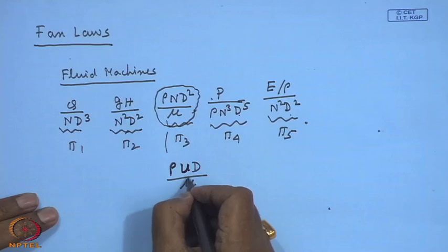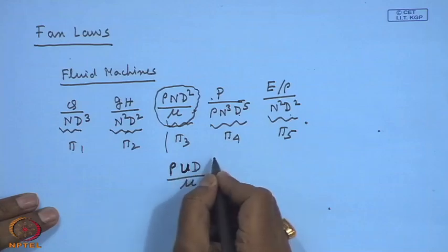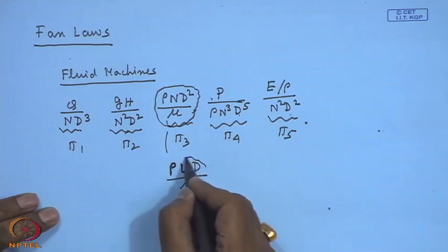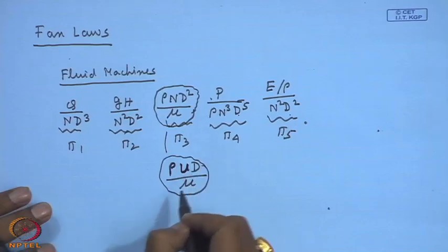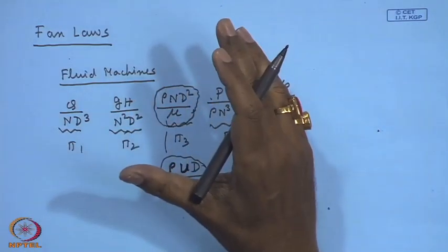So, it can be changed to Reynolds number based on other flow velocities also. Physically, it represents a sort of Reynolds number. Now, in fluid machines, the flow is highly turbulent. So, in those turbulent flows, the Reynolds number has very little influence on the flow parameters, mainly the pressure loss or any other parameter. The Reynolds number does not have much influence.